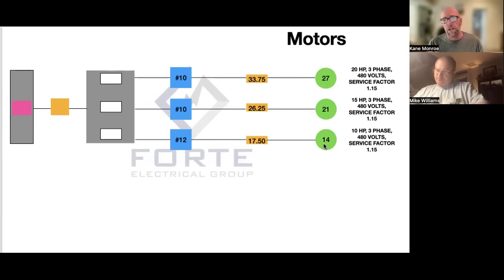And now this, you've got to remember step number 6, they want you to round down to the nearest overcurrent protection. So we've got 85 for our math. And when I look in this table, I see we've got an 80 or a 90 on our overcurrent protection. So remember, we've got to round down. So our breaker that would fit right in here would be an 80. Okay.